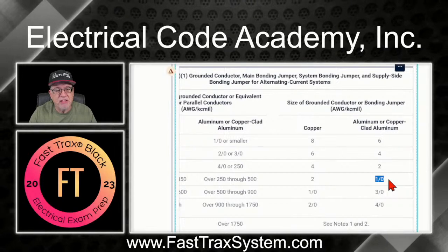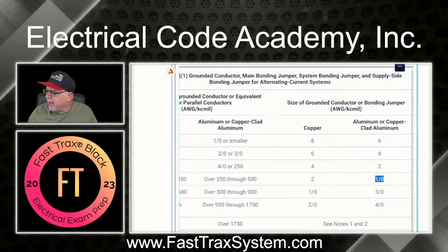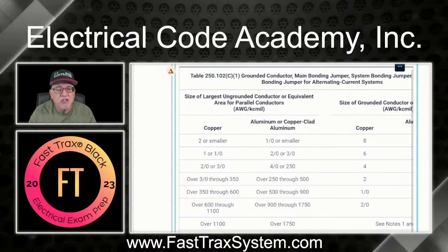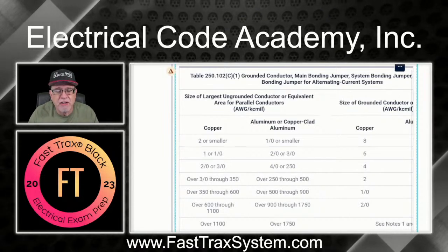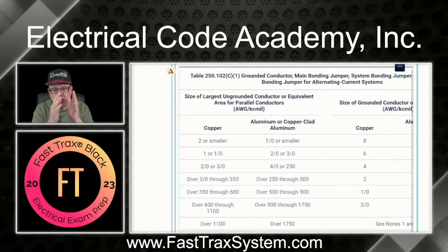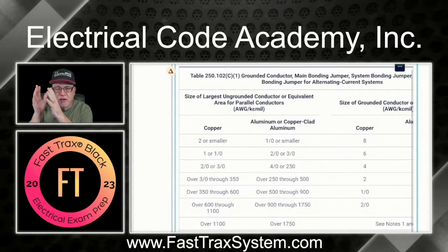Makes sense? Now, what about if we had that single raceway, like we had that picture of that wireway, that had 2 sets in each? Same thing. The only difference is you have 2 sets, which has an ABC and a grounded conductor, and then an ABC and a grounded conductor.